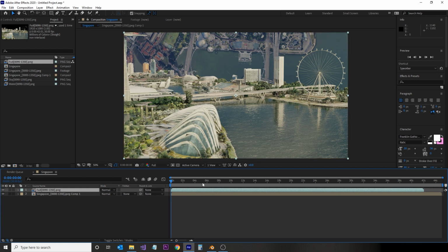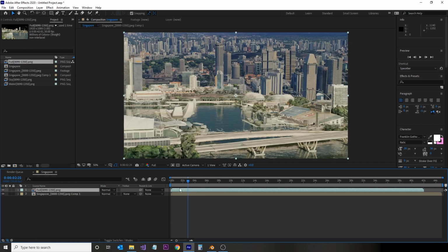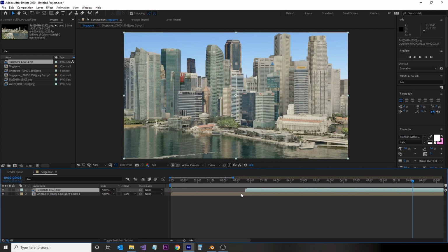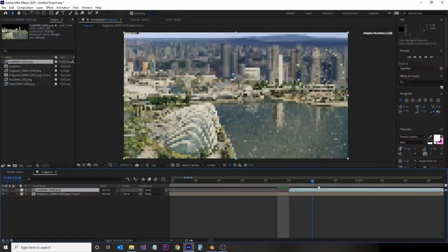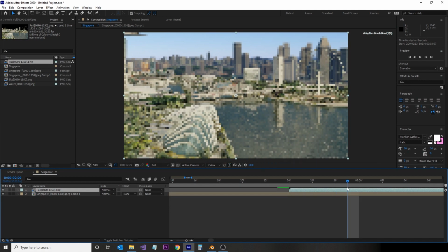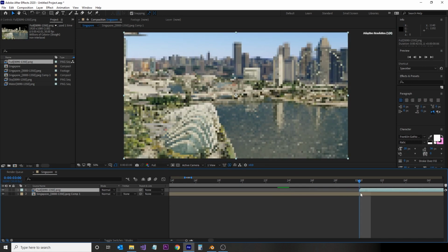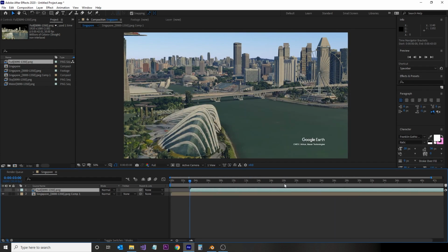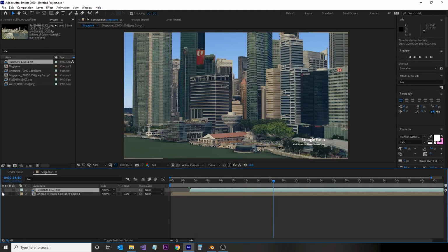As you can see, our frame sequence is off. We started at frame 90 in the Blender render. So we'll be moving our image sequence to start at frame 90 or 89, depending on the 0 point of the actual files. So we'll find an area where we can see the overlay. Then we'll just zoom in on the starting point and find the start for the images itself. So we'll be moving that across to frame 90 as a start. And we'll just hide it and view it. It looks like we're off by about 1 frame there.